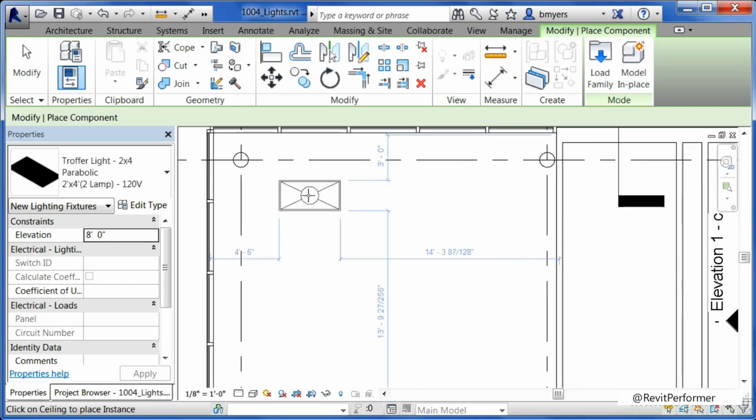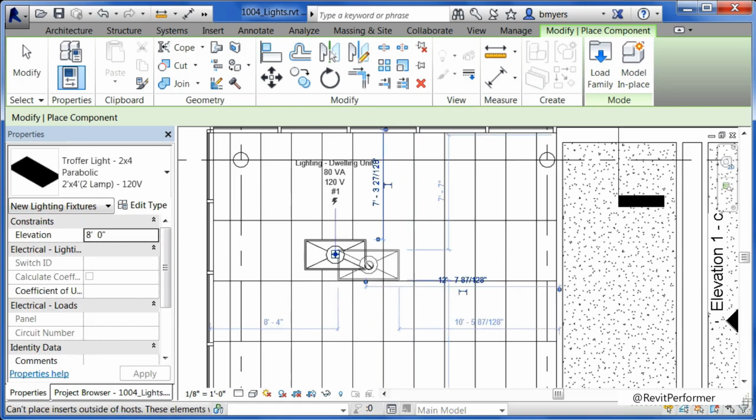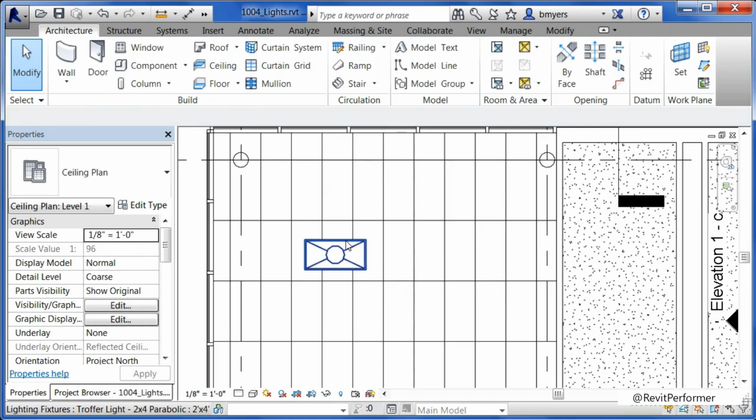One thing that you'll notice is that this light fixture is right on the center of where my cursor is. Unfortunately, that makes it pretty much impossible for me to snap to any spot along the grid. So to place this, my own trick is to come in the general area where you want it to be. In this case, I'm going to put the light right inside of this square that I'm circling myself around. But since I can't click on an intersection to place it very easily, I'm just going to click once right here. And I'm going to hit Escape a couple of times to get out of the insertion command.